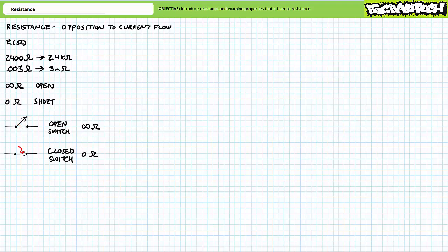A closed switch, in contrast, presents a path of 0 ohms of resistance through which current can flow. Consider a series or inline relationship of a DC source, a switch, and a light bulb acting as an electrical load modeled as a resistor. When the switch is open, there is no current flow because the resistance of the switch is extremely high. So high, in fact, that the resistance of this circuit is infinite. An open condition does not allow current flow.